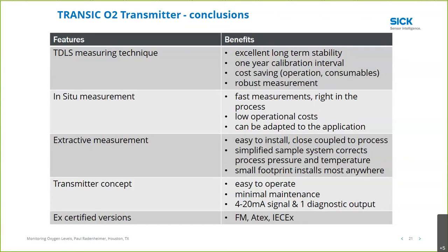As we thought might happen when we did some simple testing, in other words, flooding the sample probe with an inert gas and waiting for it to come back to the tank concentration, it took almost 24 hours for diffusion to get the headspace contents out to the transmitter itself.